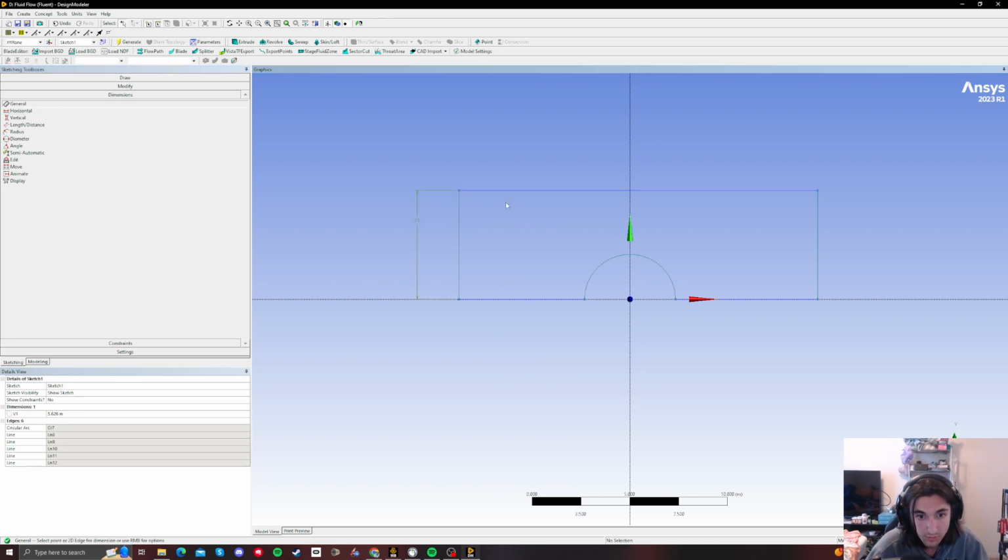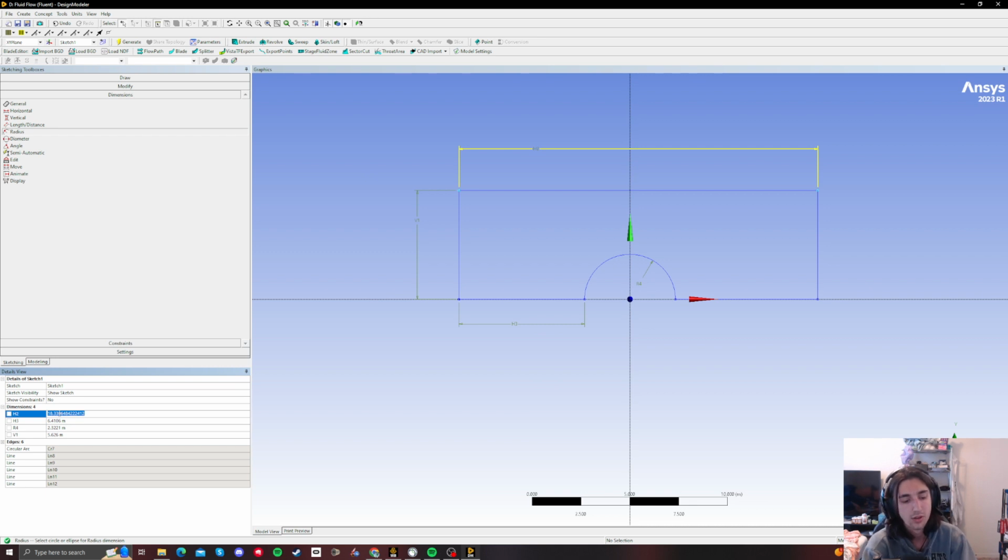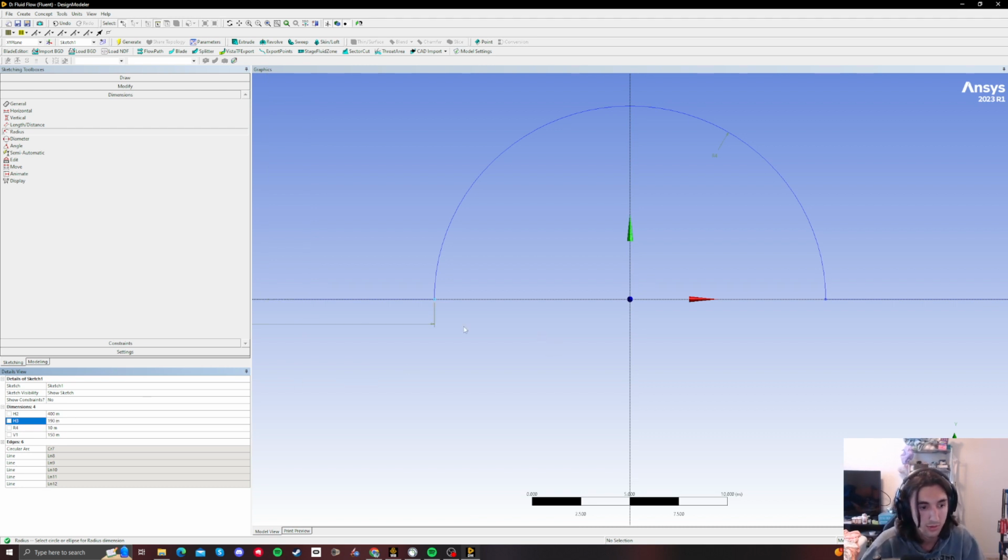So we can do this one, this one, this one, and radius. Cool. So let's make each two. I believe I did 400 meters, and I think for V1 I did 150 maybe. And then for radius, you're going to make that 10 meters. And if you have a 10-meter radius and 400 meters, then you need to be at 190 at that distance to get it perfectly centered. And wow, look at that, beautiful.